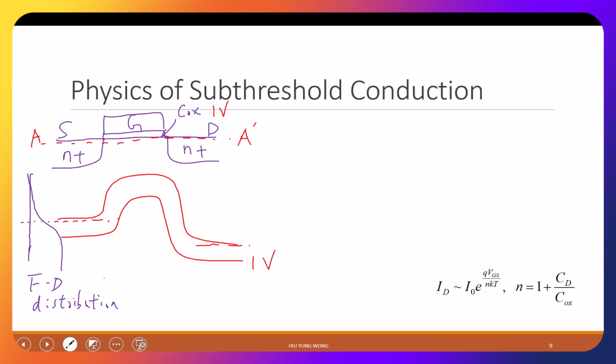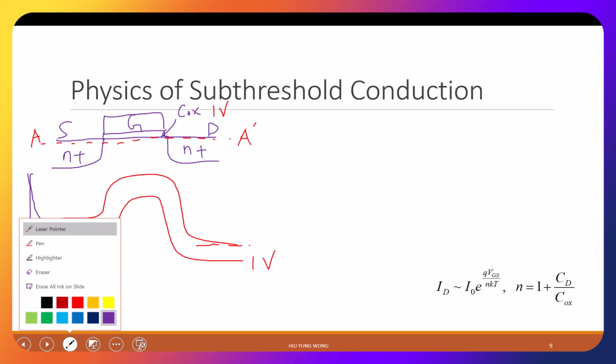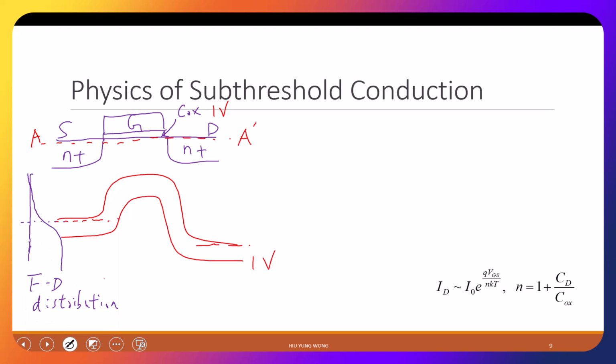It's just like the dust, right? You see when a truck drives through, you have a lot of dust on the floor, and then it exponentially decreases if you go higher and higher. That's Boltzmann's statistics, but this is pretty similar in the Fermi-Dirac statistics. Okay, so at the Fermi level, it has 50% chance that it has an electron. Above it, it keeps getting smaller and smaller. So just now you told me that I need to redraw this one.